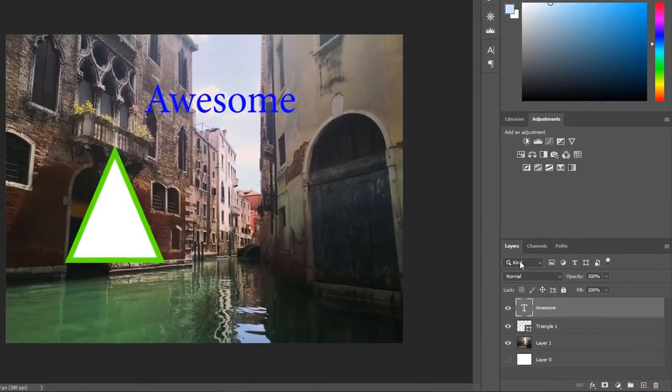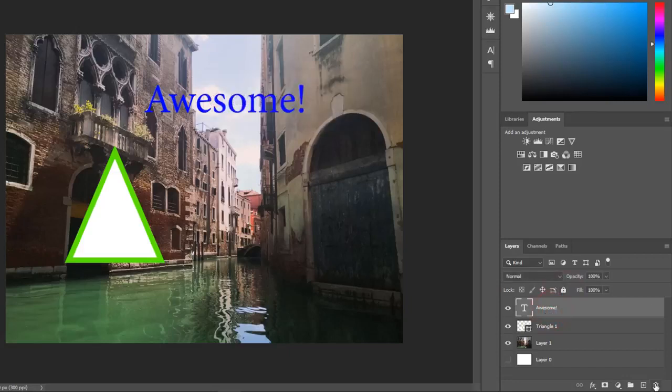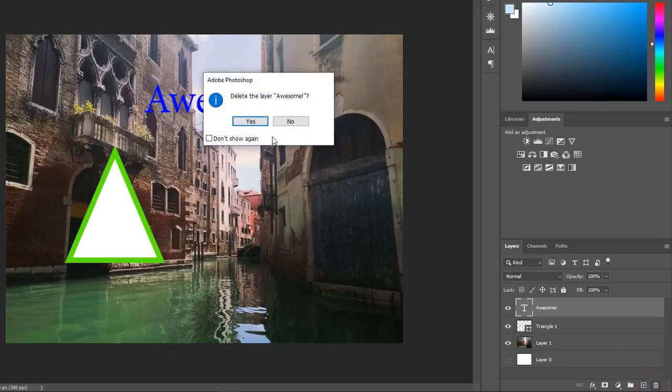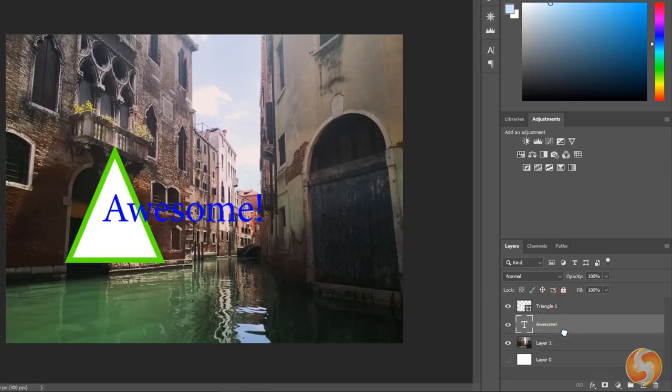Let's see how to manage photos and vectors from the Layers window. You can use the I button to hide and show each layer, and the Lock button to prevent any modification on the selected layer. Whereas, click on the Bin button at the bottom to delete the current layer. The layer position in this list is also important to set the order of visibility in case these overlap on the preview. The layer placed on top is also put in front of all the other layers at lower positions.